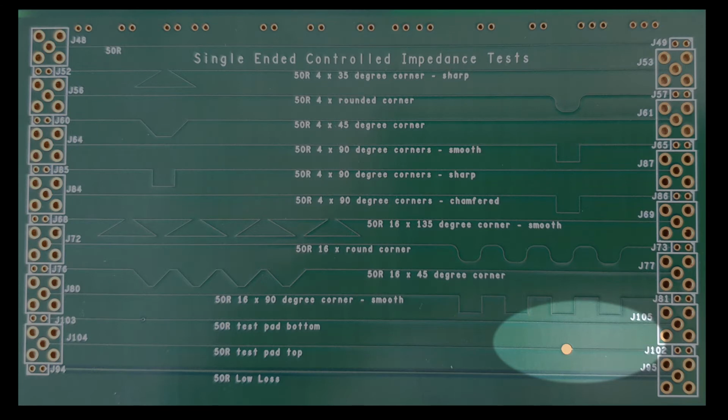The second is another 50 ohm line with a major discontinuity quite close to the end, and this has been designed to show the effects of a poorly designed coupon termination with a bad via or a thick board with wrongly designed anti-pads at the end of the trace.